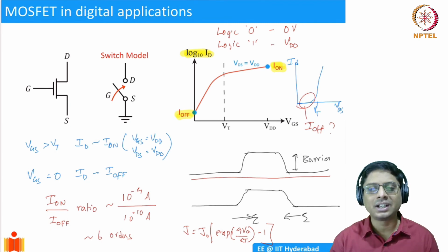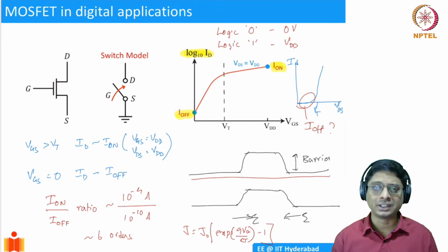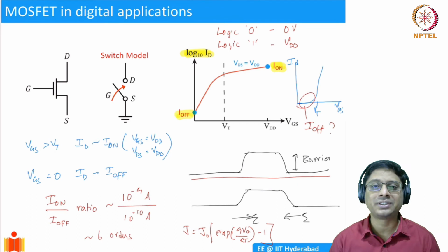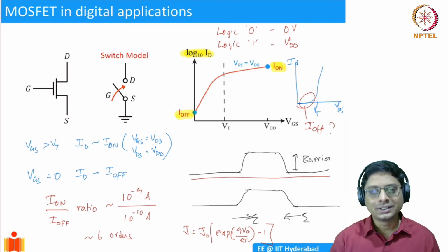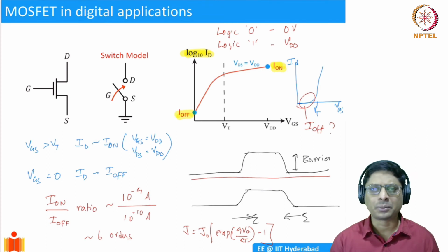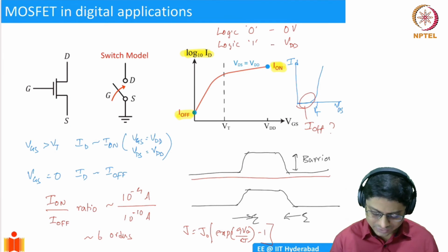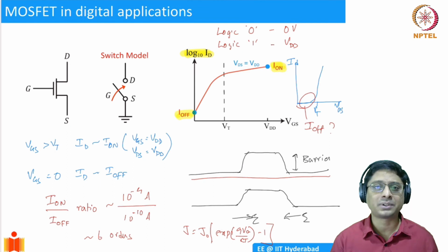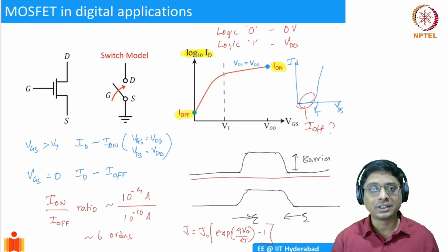But in reality, there's going to be a very small current that keeps flowing. It might be 100 picoamps per MOSFET. But then let's say there are 1 million MOSFETs in your cell phone. Then it becomes a substantial amount of current. And let's say the supply voltage is, I don't know, battery 1.8 volts maybe. Then you can compute, with 1 million transistors, about 10 power minus 4, so 100 microamps of current, and a 1.8 volt battery. So you can compute the power dissipation, the voltage times the current. That will give you the power dissipation.